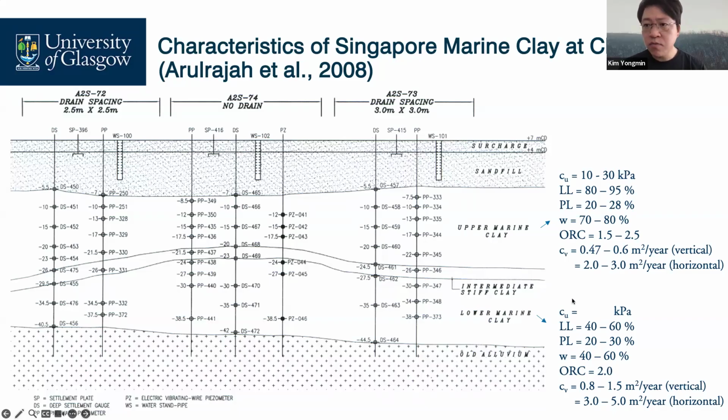And of course, we've conducted oedometer tests to get Cv. What is the Cv? And we will also measure the undrained strengths. Probably this soil keeps settling down, settling down.